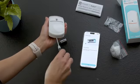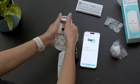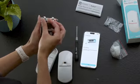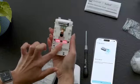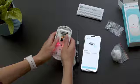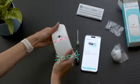You open the enclosure, remove the component with the electronics and insert the battery. The LEDs should start blinking. This means that the detector has been correctly switched on. Then you close the detector and click Next in the application.